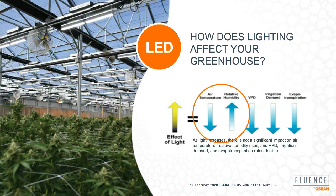But how does that differ when we have an LED greenhouse? What we see here is as light intensity increases, air temperature is not significantly impacted by the light. What happens is we get an elevation in photosynthesis, which increases our relative humidity in the space. This can cause VPD, irrigation demand, and evapotranspiration to be reduced, thus reducing the yield.